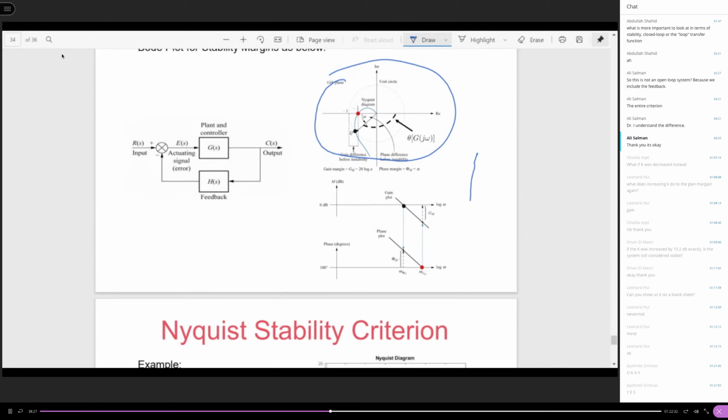And you have a good geometric, mathematical interpretation, okay? But for design, it is still the Bode plot that is easier to play with. It is always the Bode plot that is easier to play with, so just remember. That is why we need to identify where these two crossover points are going to be on the Bode plot. Yeah, you see here, this figure shows a straightforward correspondence.